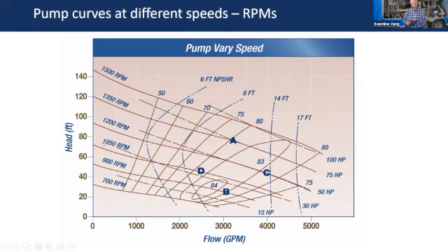If you go over here to your feet of lift head, if you only need 3,000 gallons a minute with 20 feet of lift, you go to point B here. It gives you a lot of range here that you don't get. Usually you're on the curve, full speed with the pump, and you're limited to that. Other than slowing the pump down with a pressure regulating valve or something, which can be very inefficient. And we demonstrated that earlier sometimes. Anyway, so this gives you a lot of range.